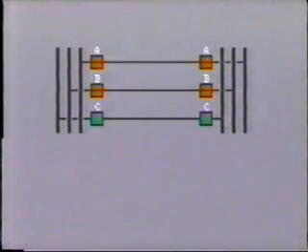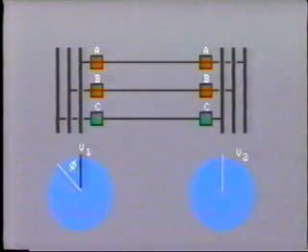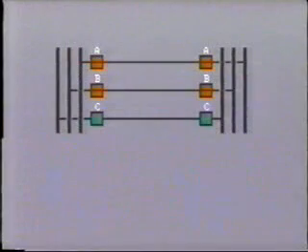For the brief interval of time that this phase is out of service, the remaining two phases will continue to transfer power and so retain synchronism and keep the phase angle difference within a narrow band. The instantaneous reclosing relay will quickly close the breakers again and restore the line to service. Of course, the same protection is set up so that a three-phase fault will trip all three phases at both ends.